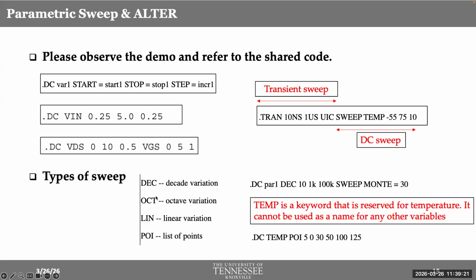Typically what we do is a decade sweep, and focus on the range that appears to be useful. For example, from 100 to 1,000, you see the most interesting results. So then you can go to 100, and from 100 to 1,000, you can do a linear sweep instead of doing a linear sweep from 1, which would be significantly more numbers.